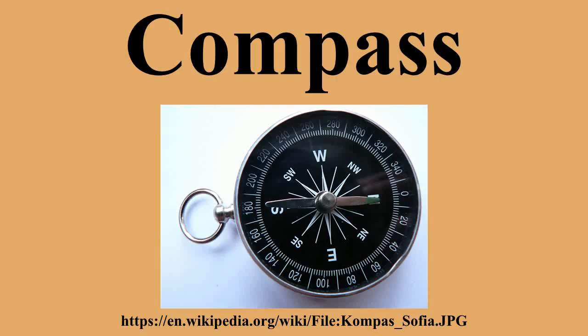Some compasses include magnets which can be adjusted to compensate for external magnetic fields, making the compass more reliable and accurate. A compass is also subject to errors when the compass is accelerated or decelerated in an airplane or automobile. Depending on which of the Earth's hemispheres the compass is located and if the force is acceleration or deceleration, the compass will increase or decrease the indicated heading.